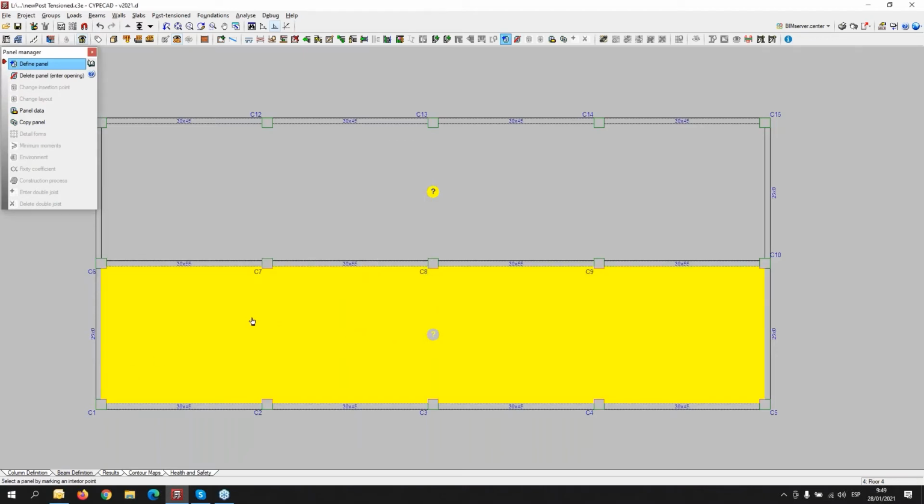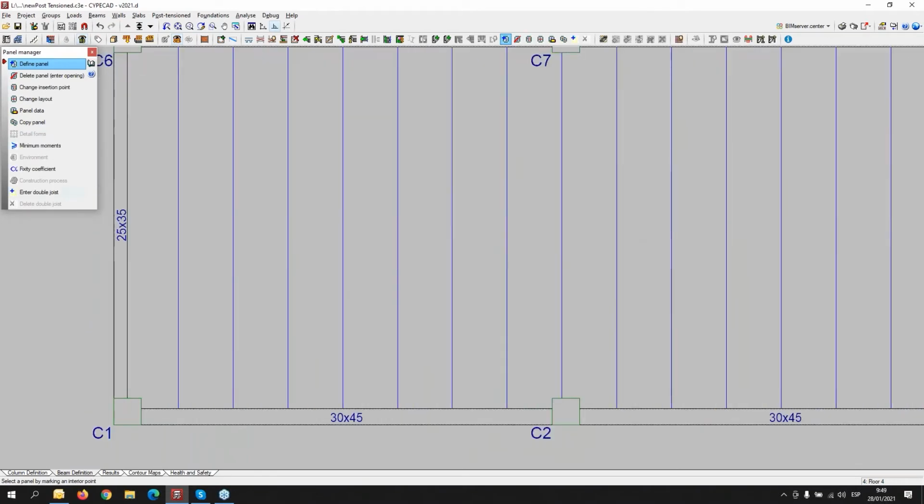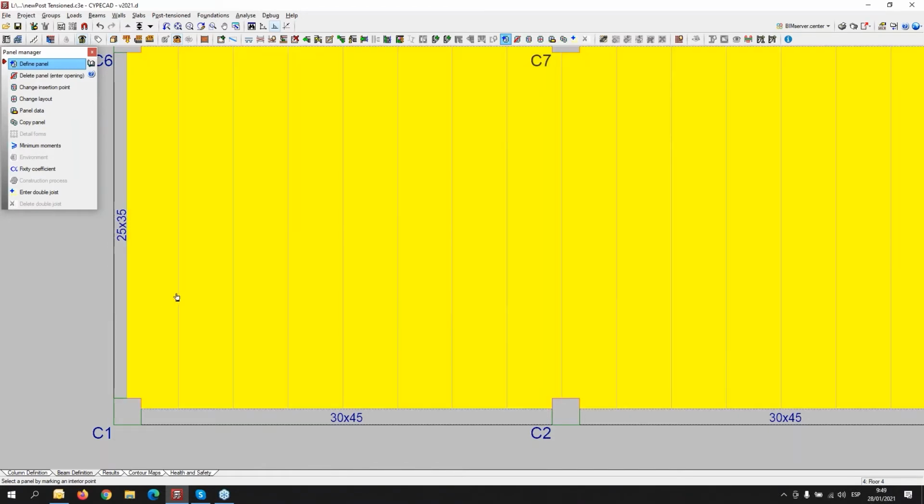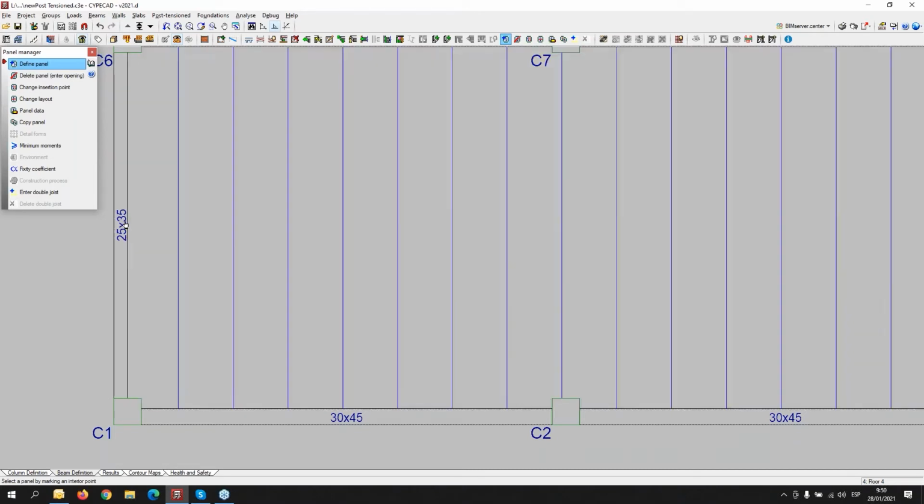and we can click inside the perimeter and click on the beam. By clicking on the beam, we will adapt the direction of the axis of the beam like the direction of the first joist. So the joist will be parallel to this beam.